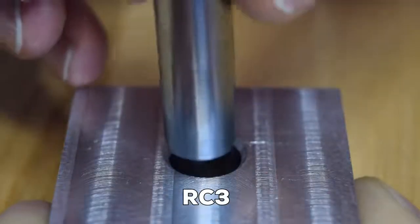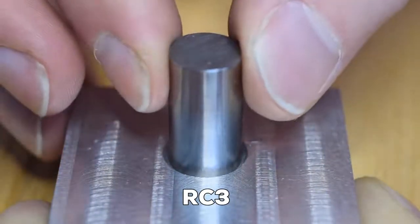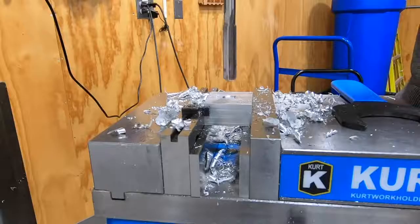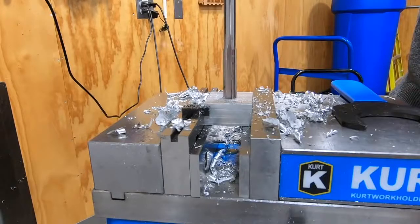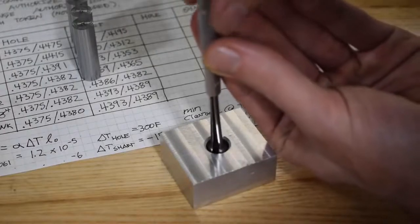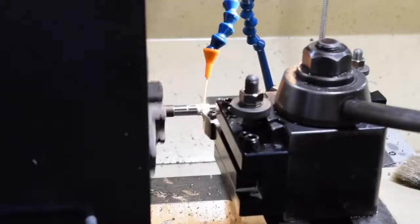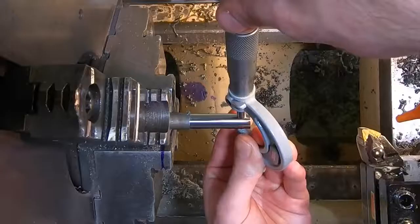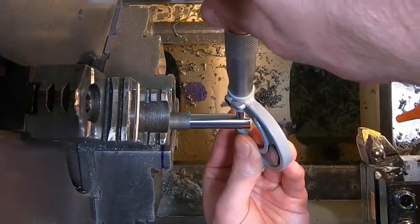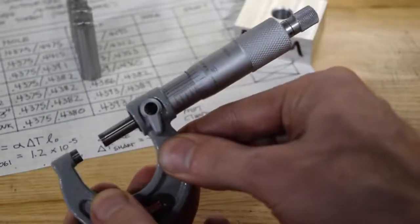This is an RC3 fit, which is a tighter running fit. In general, this fit is going to have almost no perceptible play. This hole will need to be reamed or bored. You can also interpolate it on a CNC mill, but you will probably have to update the wear offsets throughout the production run to compensate for tool wear, and you'll need to be sure that tool deflection isn't causing the feature to taper with depth. A dialed-in and rigid lathe setup might be able to hit this shaft tolerance consistently, but as with the hole, you'll need to perform regular inspections throughout and adjust the wear offsets. A lot of parts, especially flexible ones or those made of tough materials, will require grinding.